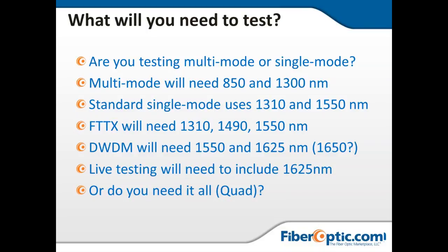So in that scenario, a lot of times what we're looking for is that 1550 wavelength, and because of the distances of a lot of those, the 1310 has too much loss, so we typically have to bump up to like a 1625 nanometer wavelength to get the distances. So this is potentially, again, a DWDM system that might be a core backbone for AT&T, Verizon, someone like that, where they need to get a lot of telephone calls, data, transmissions and all that stuff over one single fiber.